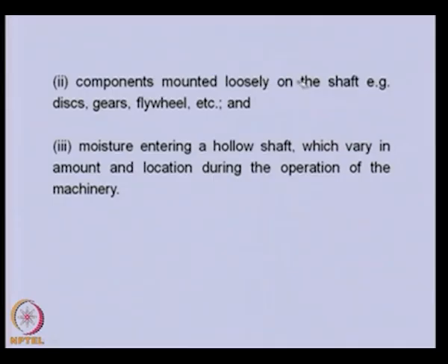Components mounted loosely on the shaft, like discs, gears, flywheels, etc. If that is the case, then also we find this particular kind of behavior in the response. Moisture entering a hollow shaft, which varies in amount and location during the operation of the machinery. So, this is another potential cause of why the response may change over time.